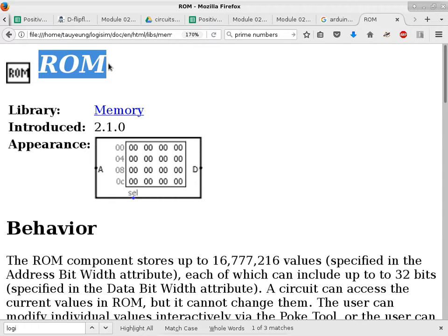Whenever you erase, the whole thing is gone. Flash memory is based on a little bit of that technology, but flash memory has two main differences compared to EEPROM. One, it doesn't need a different voltage anymore, which means your circuit board, your device, doesn't need to have some special power supply just to erase the content of ROM. And then the second one is in flash, it comes in sectors, so you can erase and overwrite by the sector.